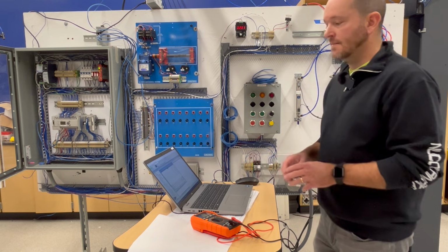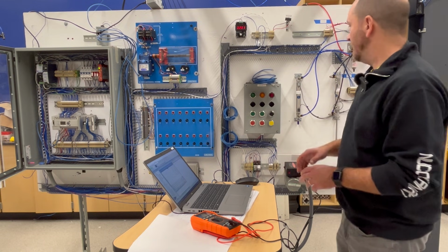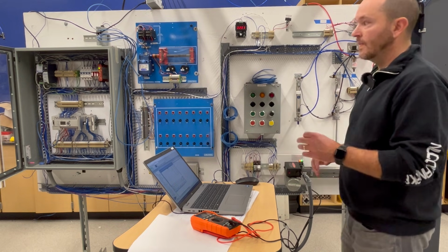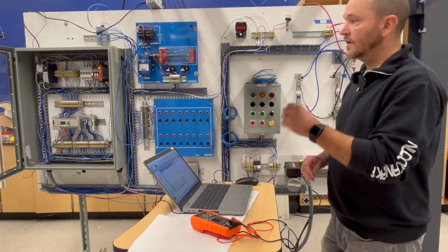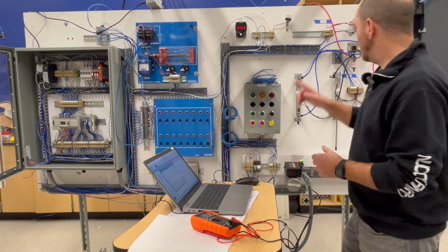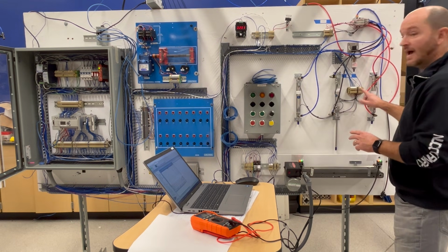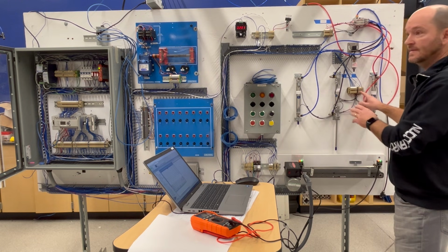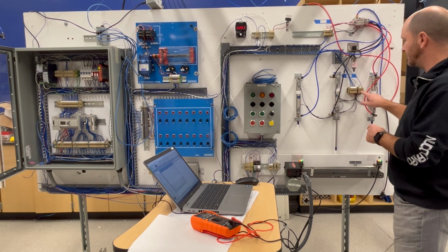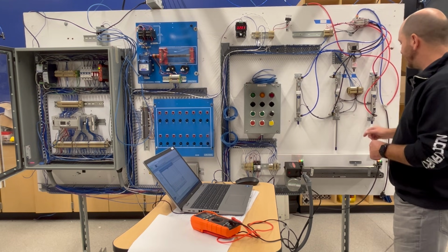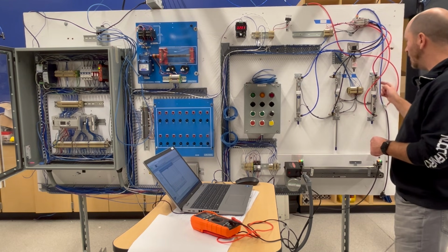So now that the schematic diagram has told me that these 4 inputs share a common, I want to troubleshoot from there. Now, one place that you could also potentially start is at the hot, where in this case the 24 volts is supplied to all of the inputs. But I know that these 2 are working.